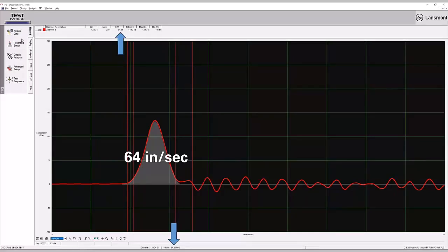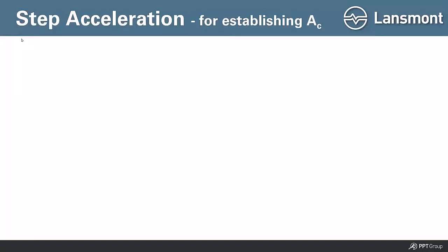And of course, computers, data acquisition systems automatically calculate all that. They do the integration and calculate that. So in this case, for that scenario with my spring mass system and that washer, that becomes my critical velocity change. I got half of what I'm looking for in my overall damage boundary testing. Okay, I got it. Now I'm going to switch things over and look at doing the step acceleration testing to determine the critical acceleration.